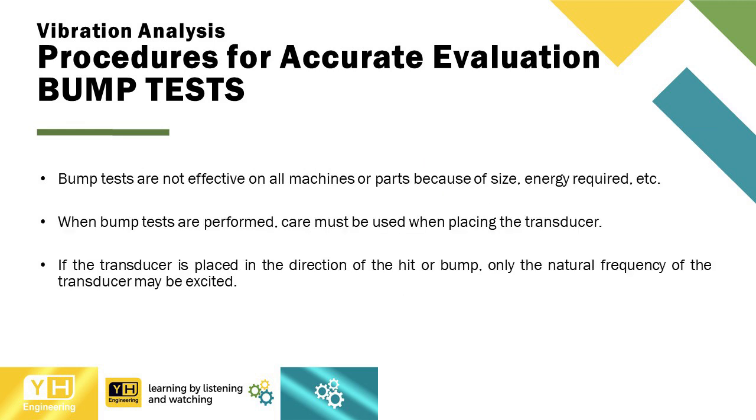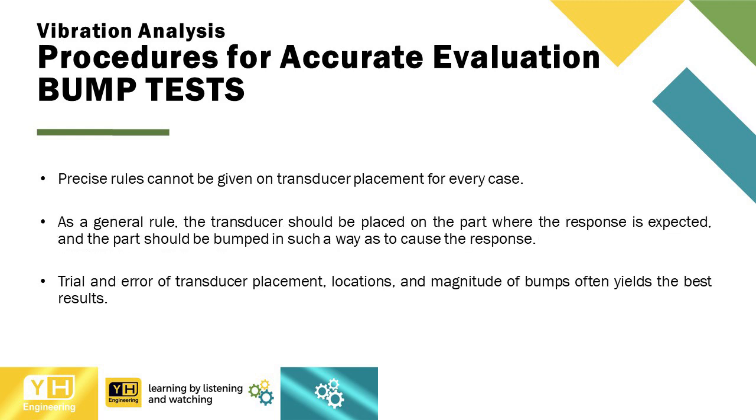Bump tests are not effective on all machines or parts because of size, energy required, etc. When bump tests are performed, care must be used when placing the transducer. If the transducer is placed in the direction of the hit or bump, only the natural frequency of the transducer may be excited. Precise rules cannot be given on transducer placement for every case.